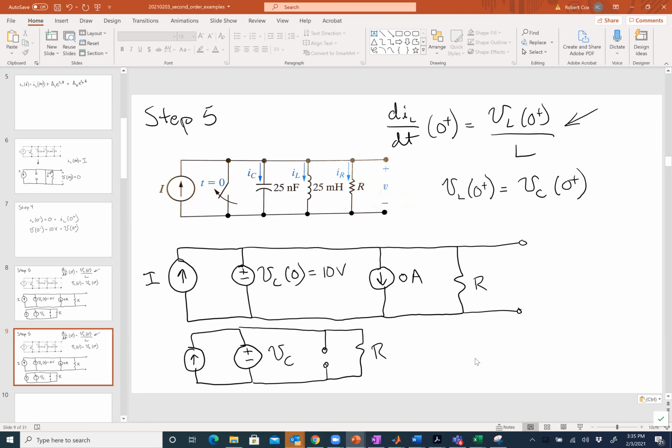I don't know how to explain. I just assumed that dIL/dt would be the same throughout the whole period in time, because that's the equation we're building. dIL/dt is a function, right? It also changes as a function of time. Think about it: what's going to happen once I get to steady state? An inductor becomes a short. So I know at that point the inductor current stops changing, and its derivative is eventually going to go to 0. It sure isn't going to be 0 initially. So we're just finding the initial start of where it is.